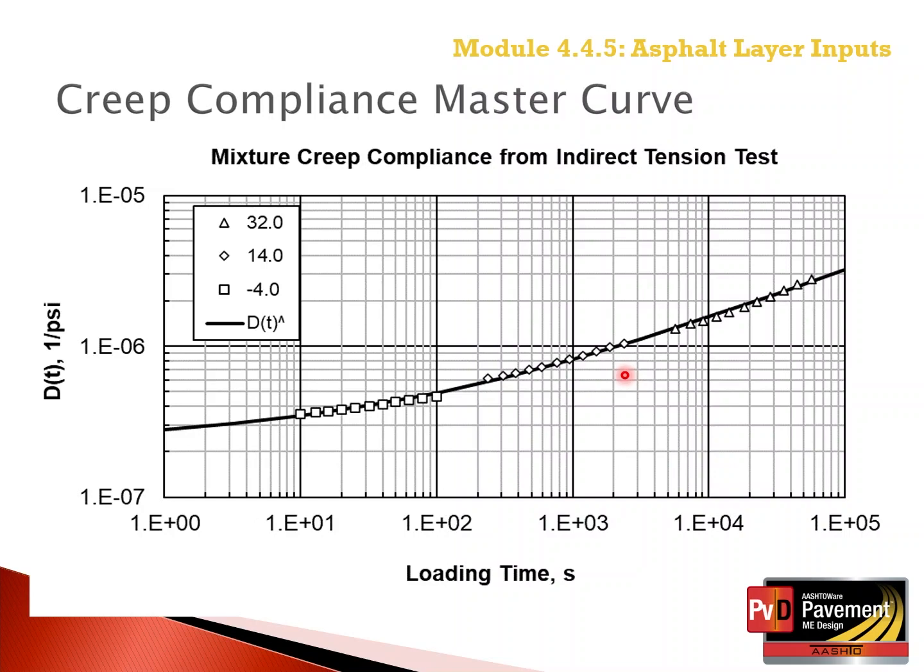Stated conversely, as the relaxation modulus, or the tensile stress divided by the tensile strain, decreases, the tensile stress will decrease as the mixture relaxes, and the lower the probability for cracks to develop. Like for dynamic modulus, most users typically use the actual creep compliance values themselves in comparing different asphalt wearing surface mixtures rather than comparing the coefficients of the creep compliance master curve, for the same reason given previously for dynamic modulus.